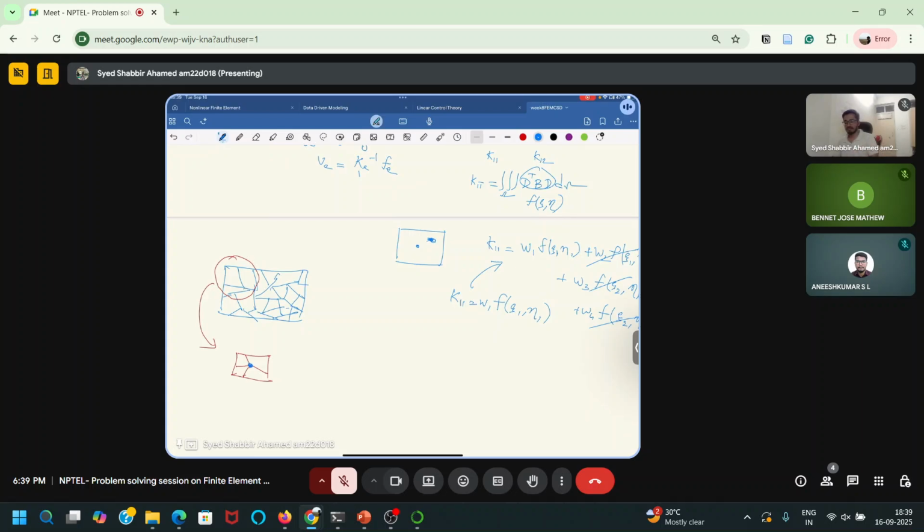You define the mesh, you define the assembly, everything you do, and then you run. What happens is that sometimes, because of some kind of meshing error, you might get an error.